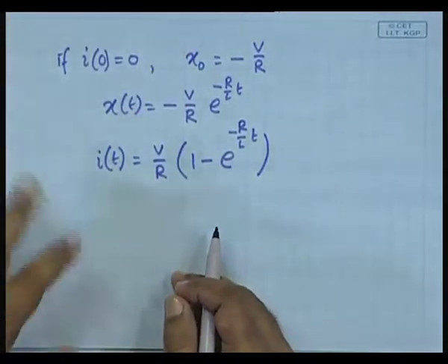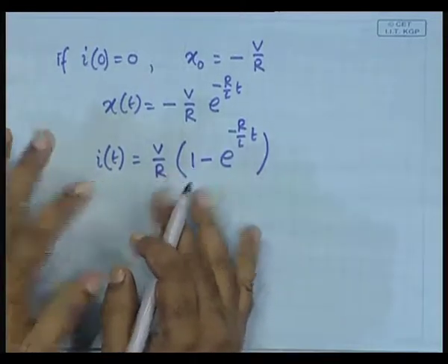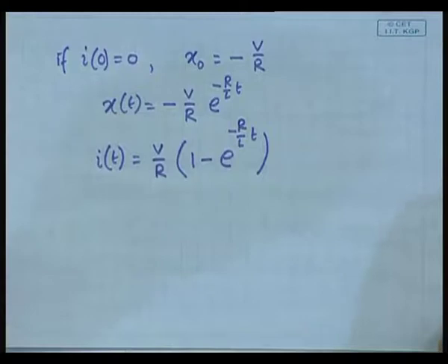What is the advantage of this route? No algebraic advantage really. It is only a conceptual advantage: what has happened is essentially that the equilibrium point is somewhere else, and my initial condition is here. So, I will do everything around the equilibrium point. We simply redefine the coordinate and obtain the solution, and then this immediately comes out. The advantage will not be immediately apparent from this very simple case, but it will be apparent when we consider, for example, a square wave as the input. What happens then? If you try to obtain the solution algebraically, it will be unnecessarily complicated.